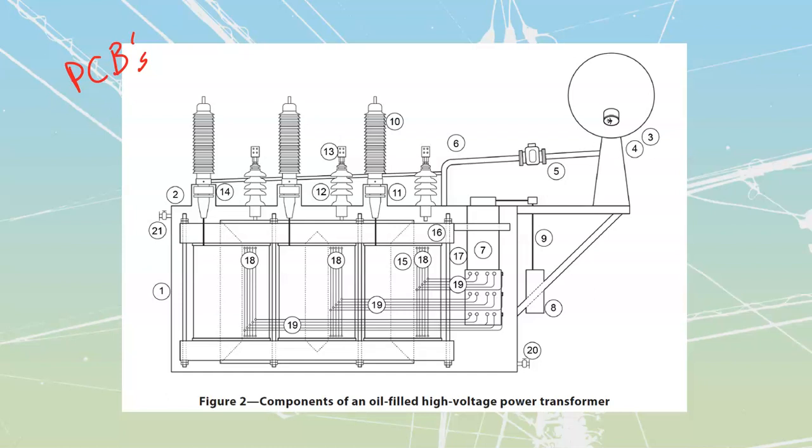They would treat the oil. They wouldn't have to place a lot, but they would place just enough in it to prevent this thing from cooking off. It really just raises the flash point of the oil, so you have to get it way hotter before it's going to be able to catch fire. Nowadays, they're moving away from it because PCBs are so highly regulated. They're looking for other cheaper methods to use.